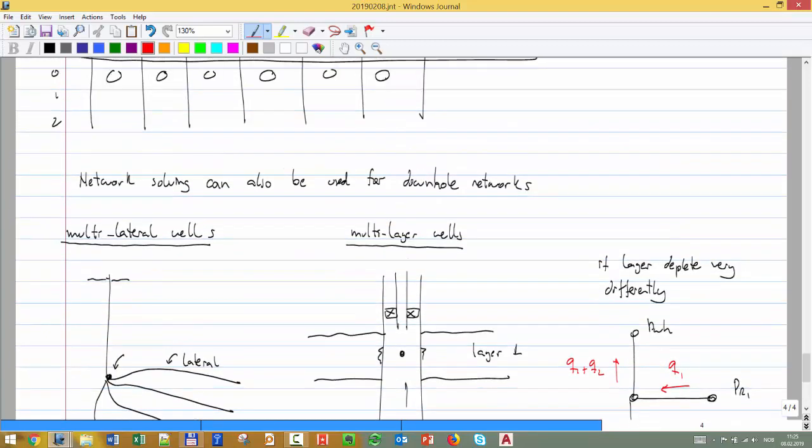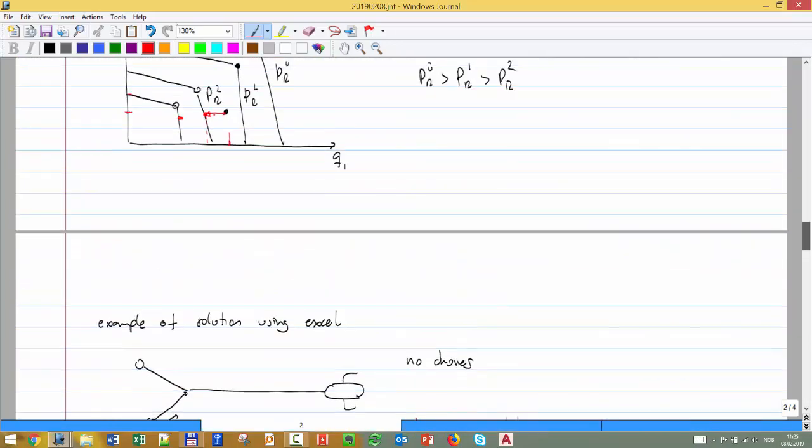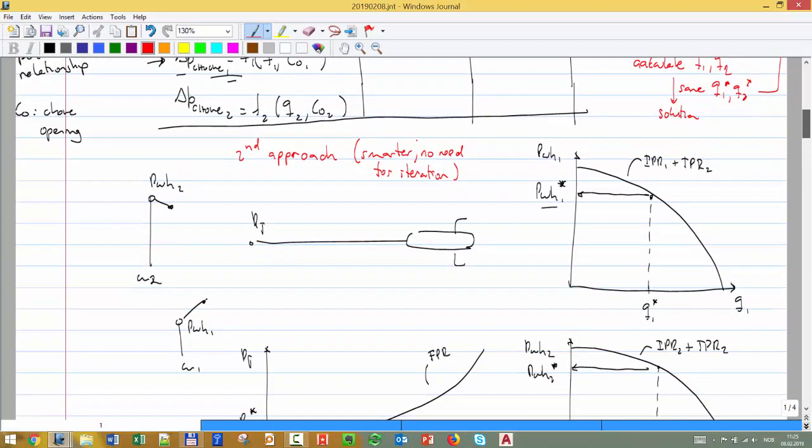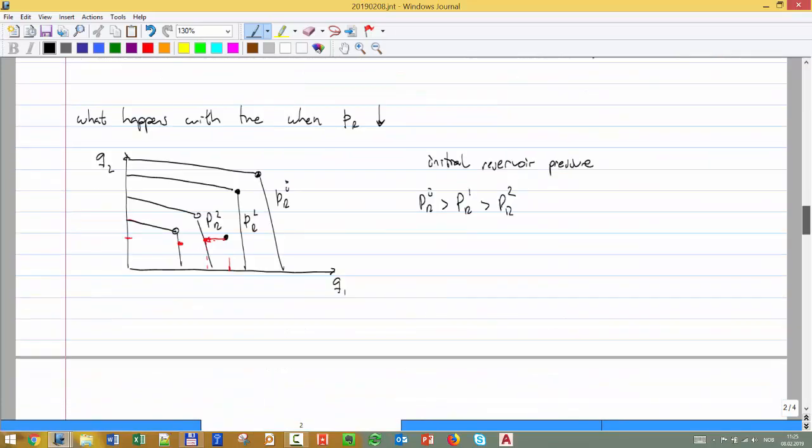So far in our system, we didn't assume that there was any change of direction. In this system here, we don't say it's possible that you can flow to the other well. But you have to be careful. What do we put to avoid backflow on wells typically? To avoid that, you know, you're producing from this one, but this one is stealing production. What do you use if you're a plumber? You use a check valve, right? One direction valve, or they call it also a Rückschlagventil.